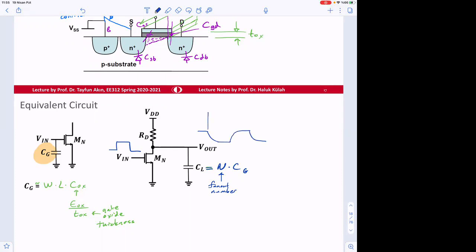With this timing, if let's say T divided by 2, T divided by 2, then F will be equal to 1 over T. Okay, so if we want to do this switching with 50% duty cycle, so T divided by 2, T divided by 2, then for each case, T fall should be smaller than T divided by 2, and T rise should be smaller than T divided by 2.